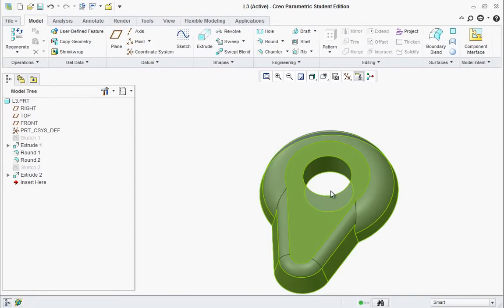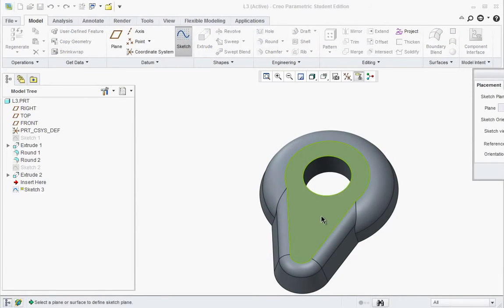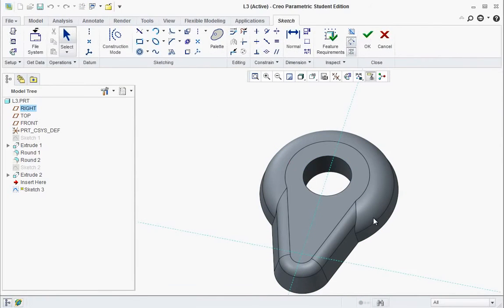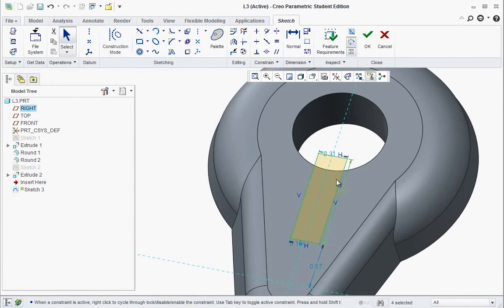Now the next thing after that is go to Sketch, select this face, Sketch, and we're going to go ahead and draw a rectangle in here. Just like that, kind of centered. Eyeballing it right now, but once we get the parameters in, it's going to be 0.25 across, and so it's 0.125 or a halfway marker, and this is going to be 0.2 to the base, and then this length, you could probably make this 2.5.